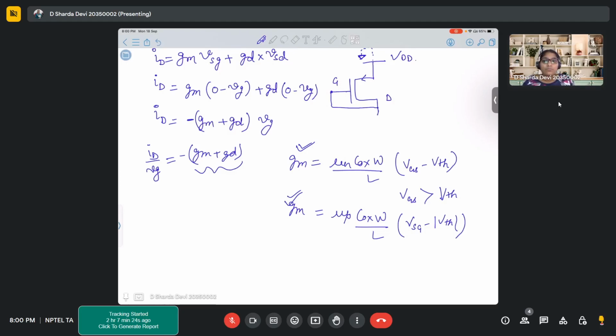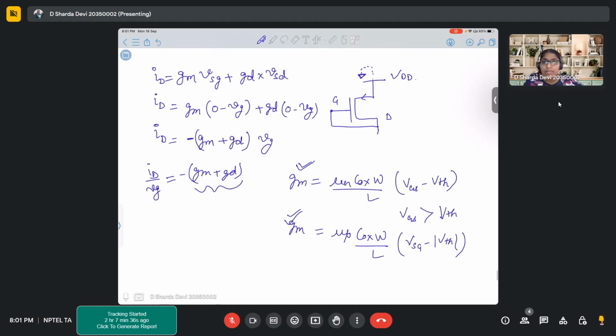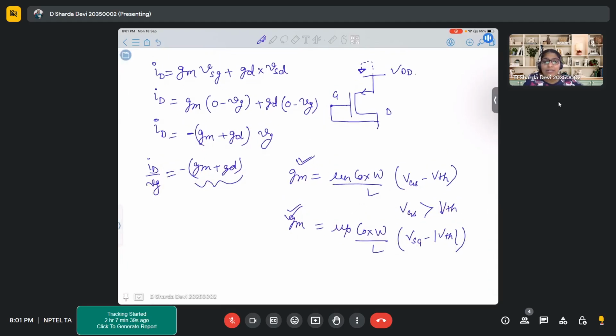Lastly, ma'am, one more thing. In the MOSFET, you have three basic elements: GM, then RDS, which is parallel to each other, and then RO, in case lambda comes into the picture. I don't follow, what are you trying to say? Ma'am, in the internal MOS circuit, GM is parallel to RDS, correct? So you are talking about the small signal model? Yeah, the small signal model.